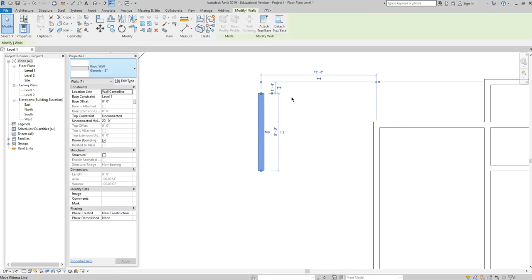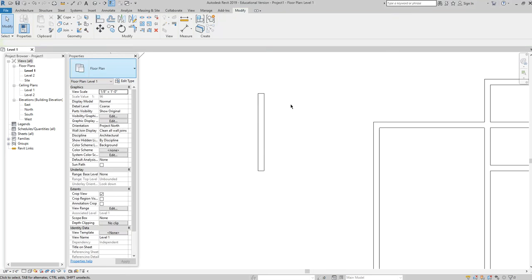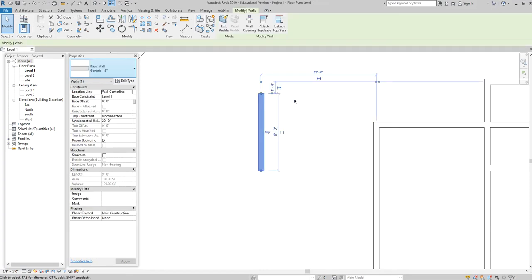But I will pin a few things down, okay? I pin important things down, like the structural grid, right? We should be pinning slabs down, really important elements in your model. The slabs, the structural grid, and if I bring in a CAD file as a link, I will pin that down. So there's maybe half a dozen things that I will pin down in my Revit model. But again, pinning things down just essentially locks them in place, okay?